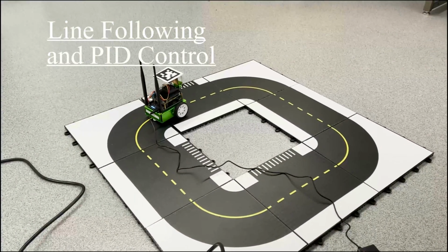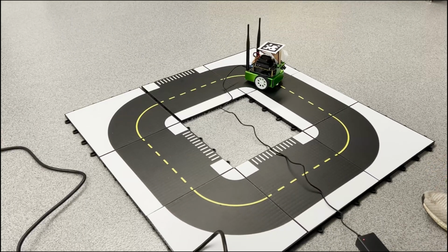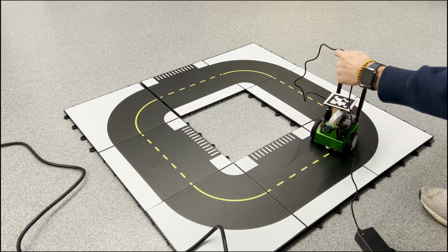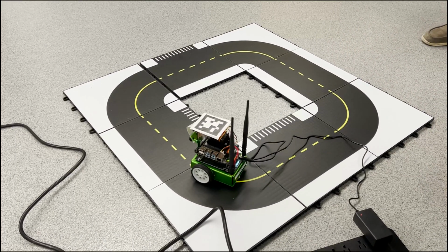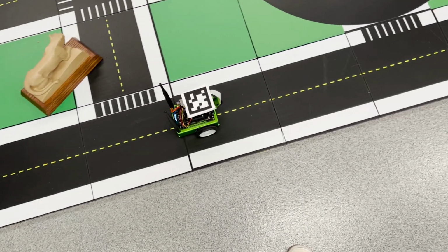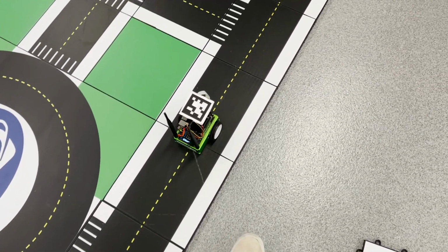Lab 2 introduced new mechanics to the JetBot's autonomous capabilities, line following, and sign recognition. The group worked to modify images captured by the JetBot's onboard camera from RGB to HSV color combinations. Code was created to work in conjunction with the HSV colored images to overlay a trace line onto the live image captured from the onboard camera.